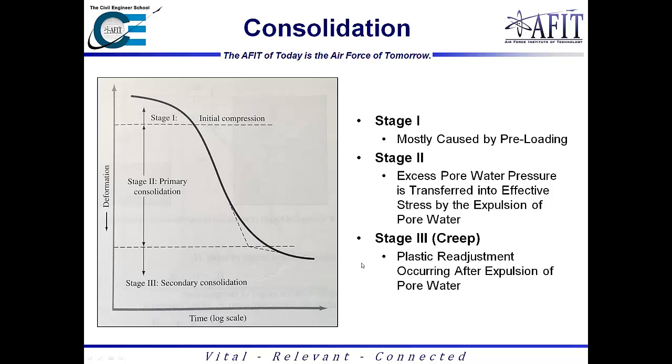And so a lot of times with the clay layers, whenever we specify 100% consolidation, typically the answer is the time it would take is unlimited, because we typically just say that it's impossible or we'll never get to that point where 100% consolidation has occurred on a clay layer. However, we could do 95%, 90, 80, or so on and so forth.